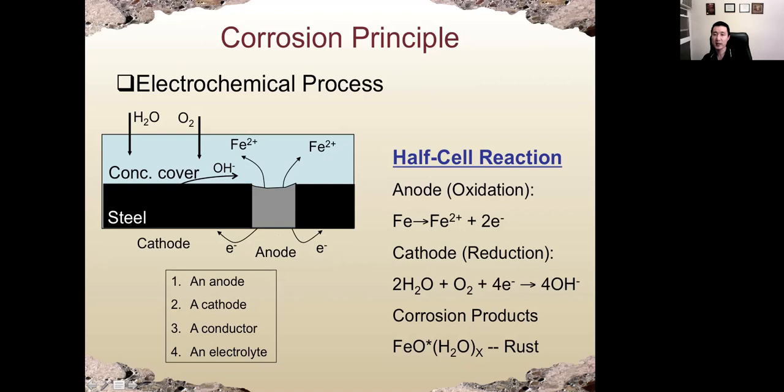In the anode area, the metal will lose electrons. If we attach zinc, because zinc or aluminum is more reactive compared with steel, these materials will serve as anode. So zinc or aluminum will lose electrons, and steel will be protected. All the steel reinforcement now becomes cathode, and that's why we call that cathodic protection.